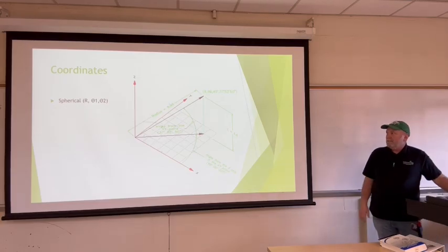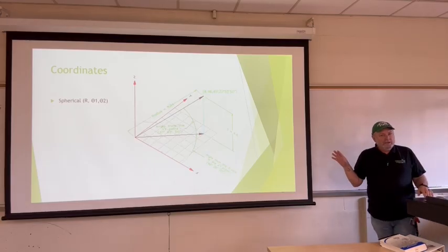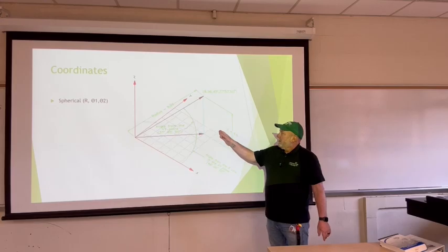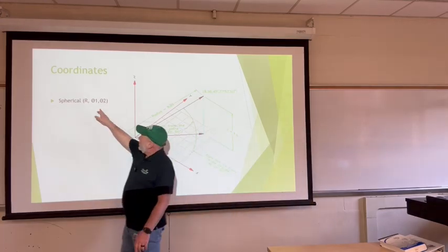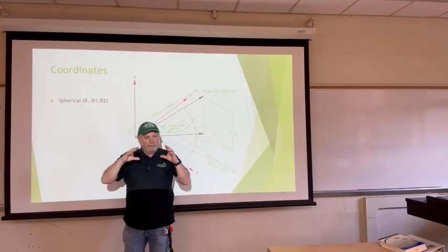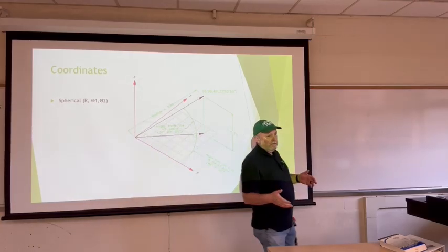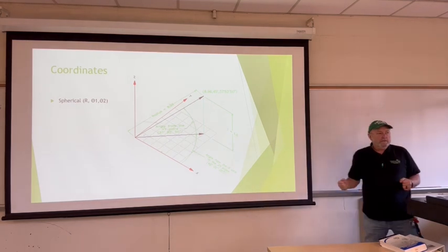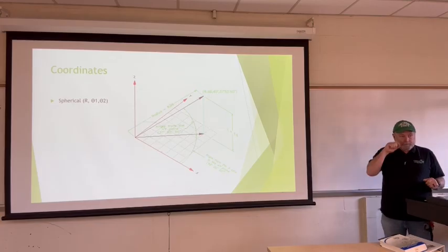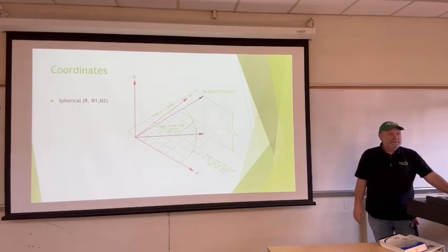It is a tricky concept to think of, and we will not really do any true hand calcs of this nature, but yeah, a longitudinal angle, a latitudinal angle, and essentially the radius of the Earth, or from the ellipsoid, and there's a flattening. So that would be looked at as a height in geodetic speak. Lat, long, and height. Spherical coordinate. Maybe I need to get a better graphic to help represent that one too. That help?